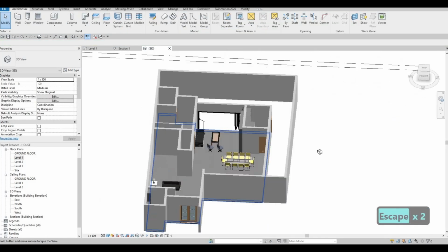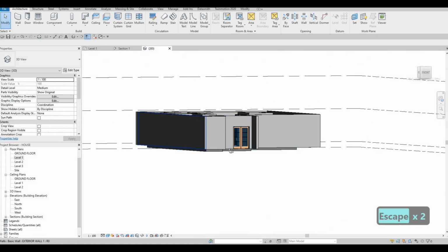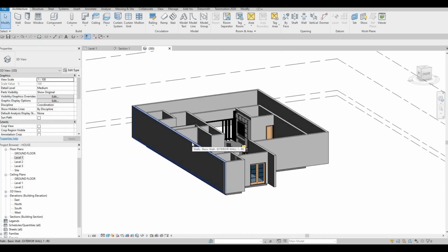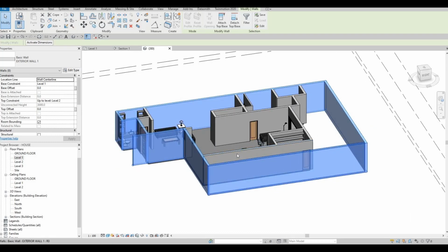Now we have our floors for this one, and obviously we're going to extend this one up to the ground. So we can now click on tab. It will select everything under our exterior wall, and then let's add this one as well, because this is exterior wall as well. So now it's not letting us, so what I'm going to do is hold on control.